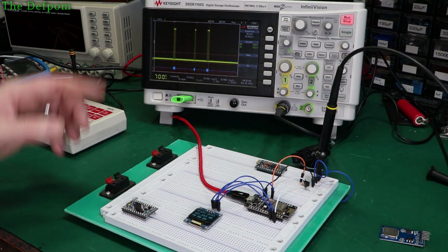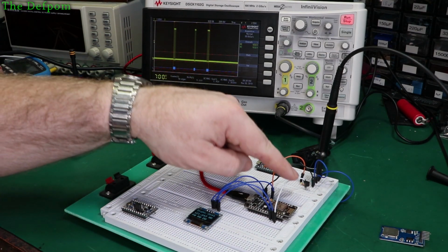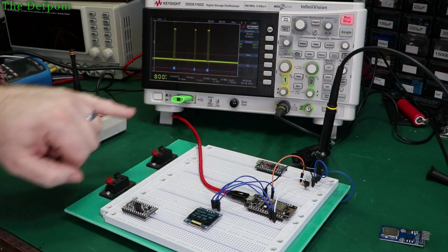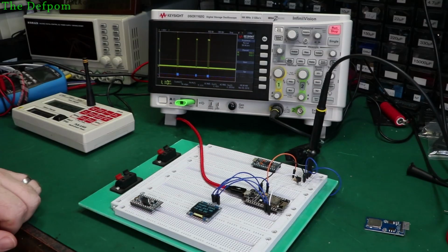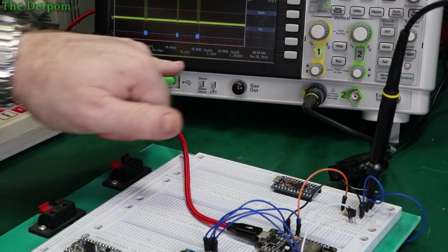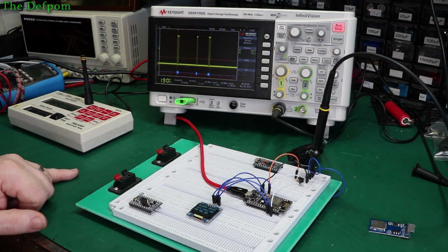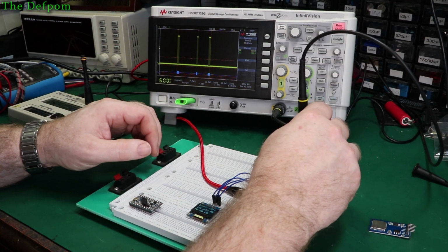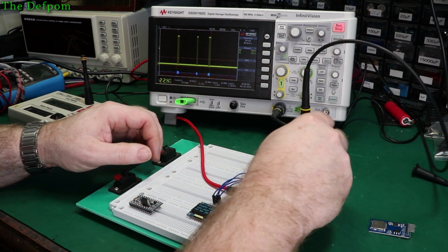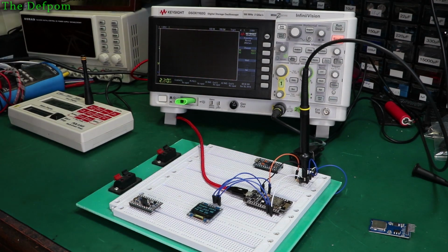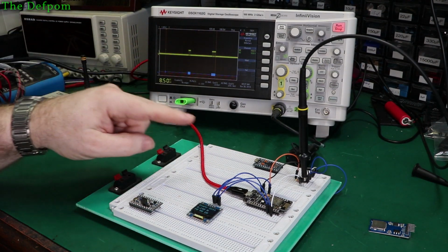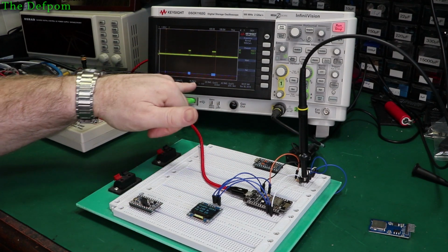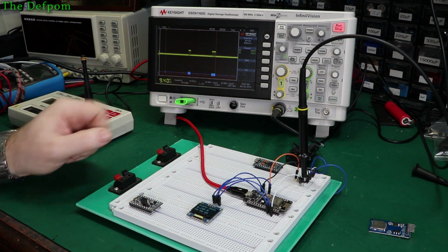Right, so as I said before, this is an inverted display, so I'm going to show you the output level of this. As you can see on here, that's 5.1 volts peak to peak. You can probably just see it. Yeah, right, 5.1 volts. So that's the level coming out of that device. Now if I reprobe somewhere else, like right here instead, I'll do another single capture. Now this is after the resistor going into the base of the transistor. So you can see the voltage here is 1.13 volts peak to peak going into the transistor.